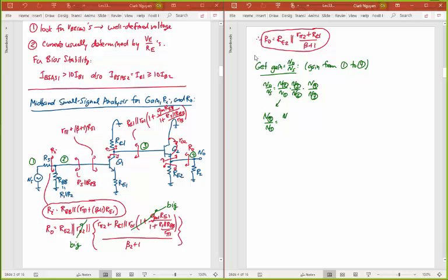And so this, of course, is the same as my source voltage, Vs, to V2. And in this case, it's obvious what that is here. This is just going to be the voltage divider between Rs and this resistance Ri. So Ri is all of the resistance looking in this direction to ground, right? And so basically I can just write this as Ri over Rs plus Ri.